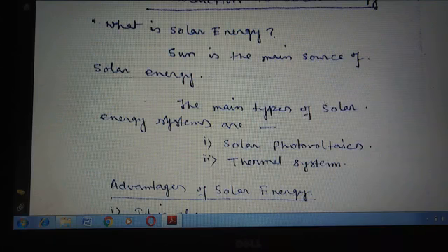These modules are again fabricated in series-parallel combination to develop the photovoltaic array, which is generally used in solar photovoltaic plants to supply a tremendous amount of power for residential and industrial applications. Generally, 36 solar cells are connected in series to make a solar photovoltaic module.